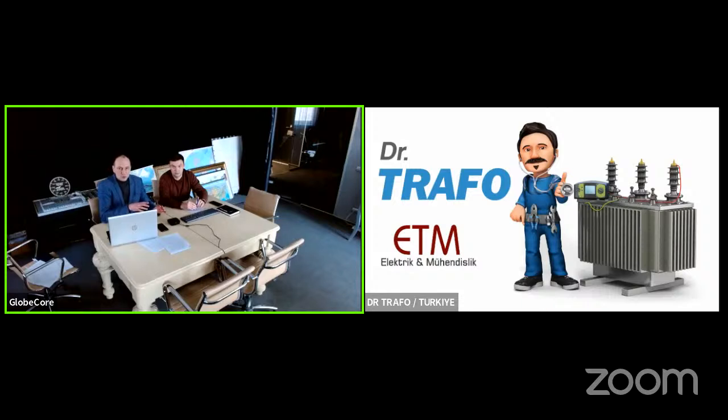In regeneration mode, you'll be able to operate with the maximum capacity of 2,000 to 3,000 liters per hour. And once again, it depends on the initial oil quality. I would like to stress that the quality of the regenerated oil depends on the contact time between the oil and sorbent. It means that you can increase the capacity of the regeneration machine, but at the same time, you will decrease the quality of the oil.